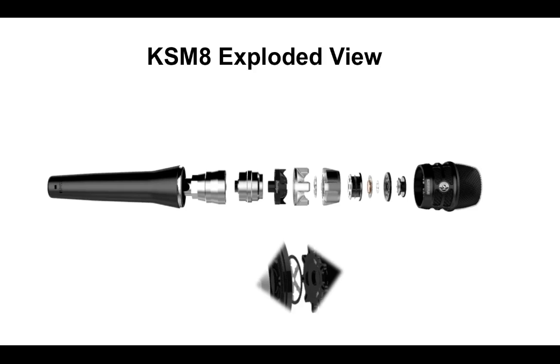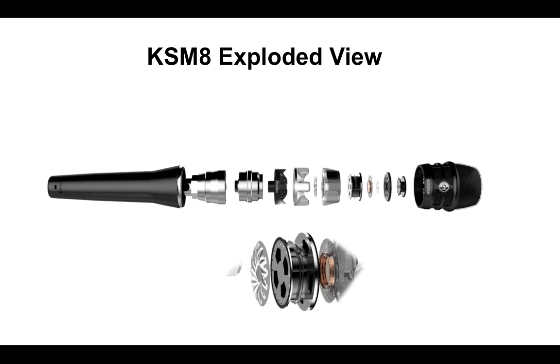So we designed this new stabilization system. It gets glued to the top of the dome of the actual front diaphragm, and basically reduces high frequency handling noise and keeps the system moving axially in the response that we want it to.